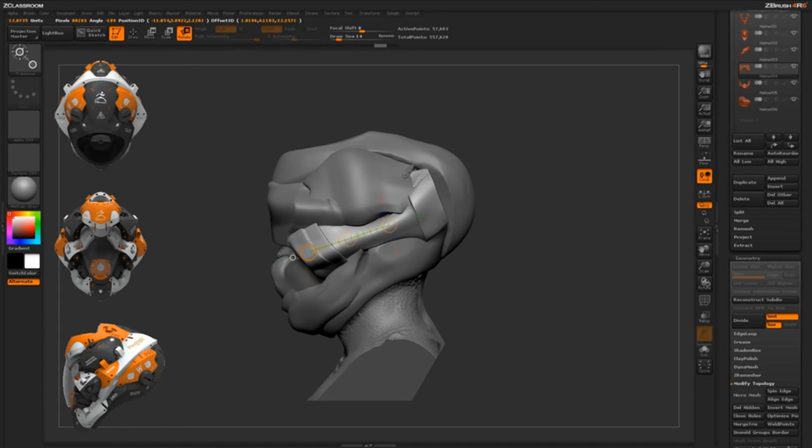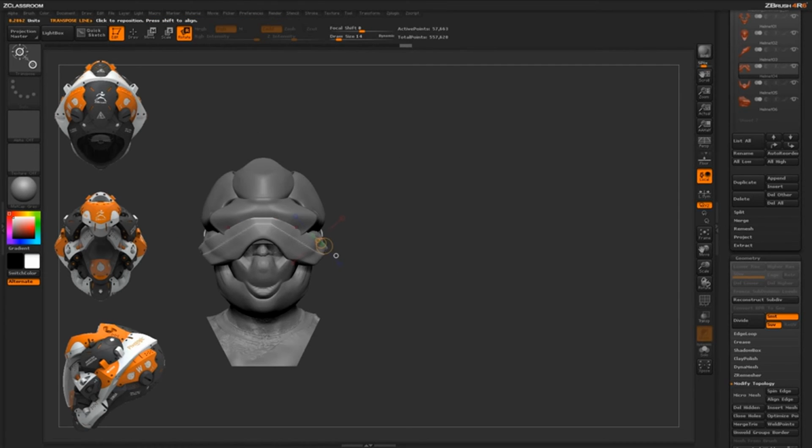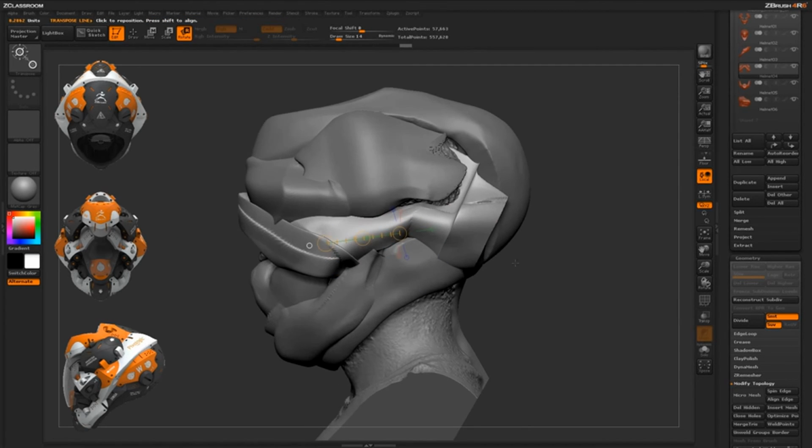The other alt functionality that's also good for cylindrical objects for bending them is if we just hold alt and then grab one of the circles here, it's going to bend off this circle. So think of this as almost a bone structure. So you'd have your knee joint and then you'd have your ankle joint, and when you hold alt and click the structure here, it's going to bend it like an ankle. So you can see here it's constraining that structure there, and you can do it both ways. Just hold alt and then click that inner circle, and you can actually start rotating these pieces out. So you can get these interesting bend shapes as you go across your model.